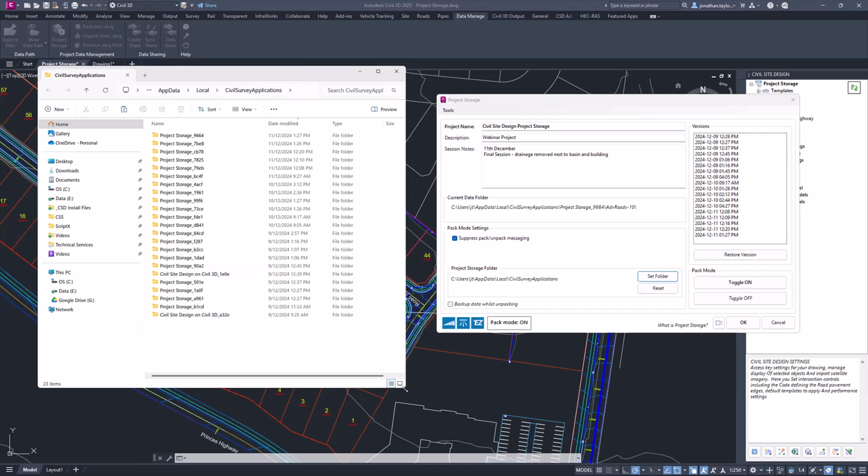And Jonathan, you've got it up on the screen now, which is perfect. Because there are unique locations for the data folder every time you open, it would actually be looking at an older version of the XREF location. And two, you're kind of in chicken and the egg territory. If you've got an XREF bound inside a data folder that's inside a DWG, the XREF tries to access the XREF location before the data folder gets extracted and can get a bit messy.